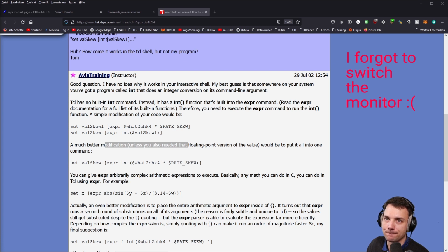So what's missing? If we say that's all good, we can now go and put in the boundary conditions. And here comes the fun part, right? Because depending on the mesh size, we really don't know how to put the force in the middle of the beam. This is what we should have done in the first place. And this is also a good thing to see here, because now those commands will not really work.